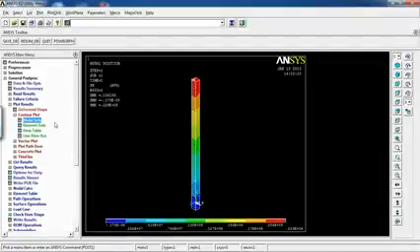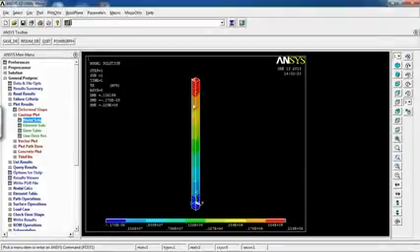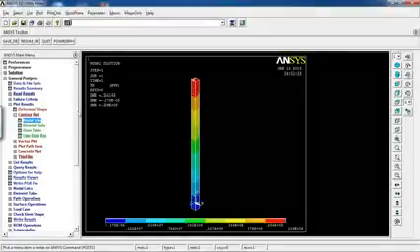The other way to do this analysis is to define a 3D model from the beginning. So let's define a cube of the same cross-section area and the same height, and then apply the same loading conditions in terms of weight and temperature, and we will see in the next lesson how the expansion of the beam in y direction according to its own weight and the temperature that is applied to it will change the cross-sectional area of each point of this beam.